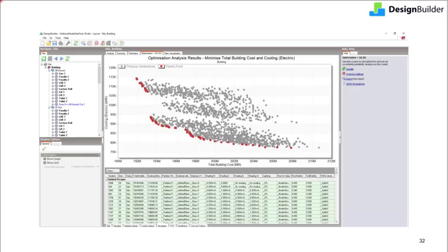The complete optimization run is shown here. The optimization was run for about 3,000 simulations and took approximately 36 hours. Analyzing the results and point cloud, the project team answered key questions related to trade-offs between system efficiency and envelope performance, use of shading versus high-performance glazing, and they also assessed the most efficient shading strategy for each orientation.